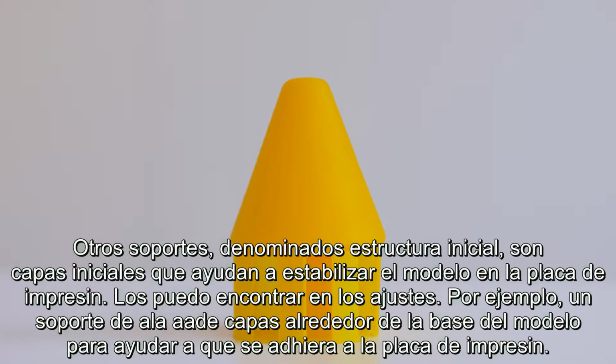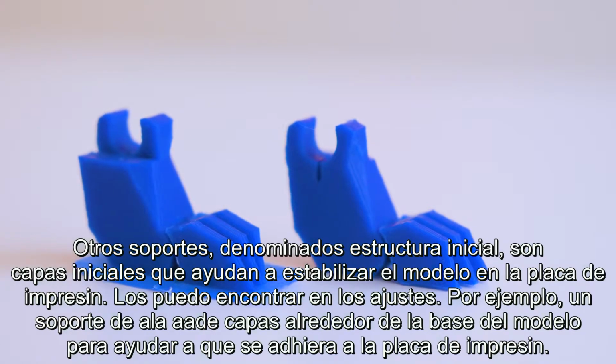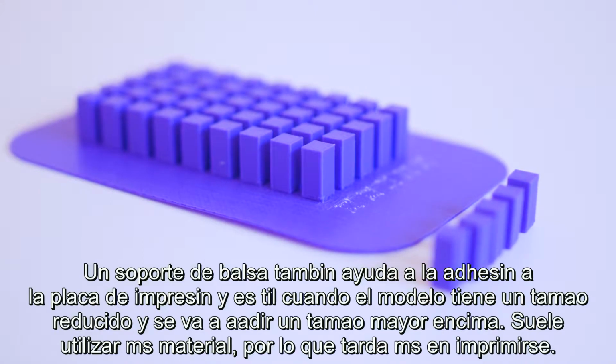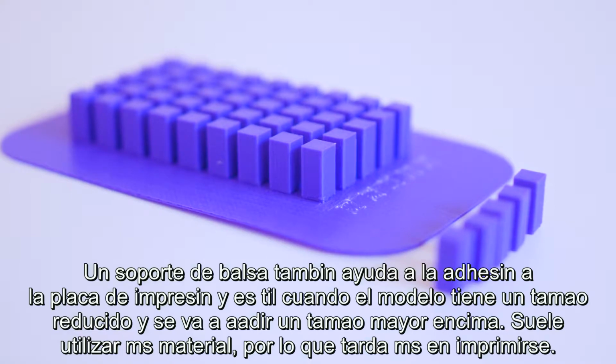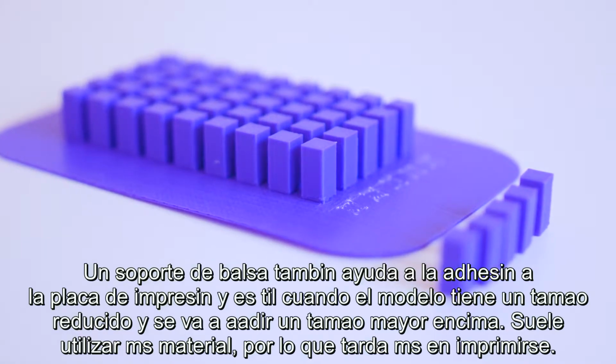Other supports, called initial structure, are initial layers to help stabilize the model on the print bed. I can find them in the settings. For example, a brim support adds layers around the base of the model to help it adhere to the print bed. A raft support also helps in adhering to the print bed and is useful when the model has a small initial footprint and a larger size is layered on top. It uses more material typically and therefore can take longer to print.